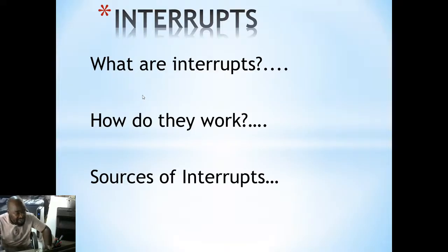When it gets an interrupt, it leaves whatever it's doing in the main function and goes to what we call the interrupt service routine, executing the program under it. It performs the function it's supposed to perform when it gets an interrupt, and when it returns from the interrupt, it goes back to the main function and continues where it left off just before it was interrupted.